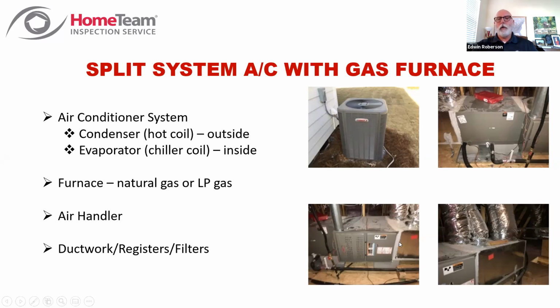So the air handler is drawing air from the house, from the return vents, and just coming right through these. So when you're burning heat, your heat source is here. When you're cooling, your cool source is here, and you just use the same air handler to move that air through the home. And the rest of the system is just ductwork and registers and filters.